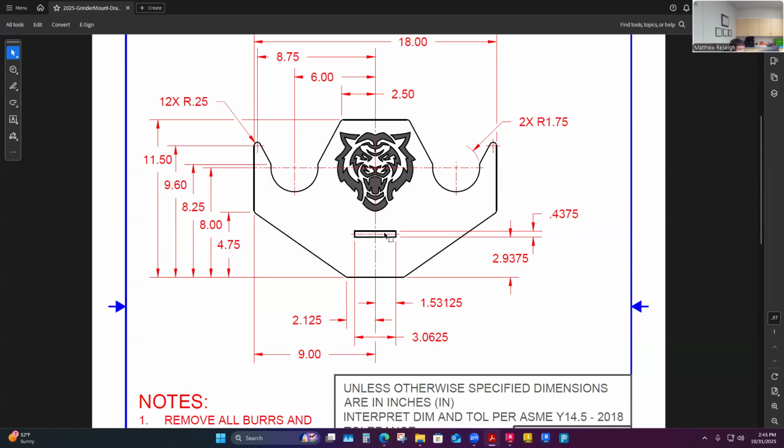And so I've put a 16th of tolerance clearance on these. That might not be enough. I hope I don't have to make you grind these out. I can't remember what material they're going to cut these out of, but the kerf won't be... You guys know about kerf, how when you flame cut stuff, there could be a little angle to it, just slightly. And so if this isn't enough tolerance to slip that over, I hope I don't make a bunch of grinding. But it's a 16th bigger all the way around than the part, which is pretty tight tolerance. That's why I'm worried about it a little bit, but it's not super sloppy.